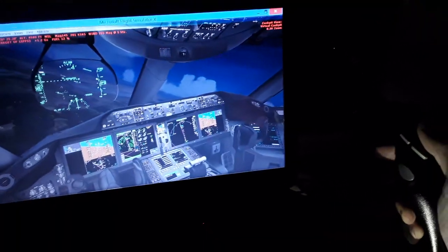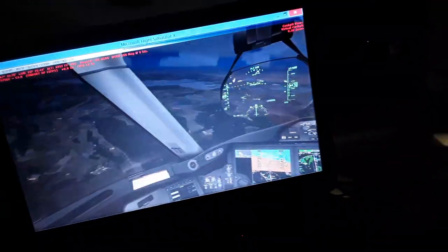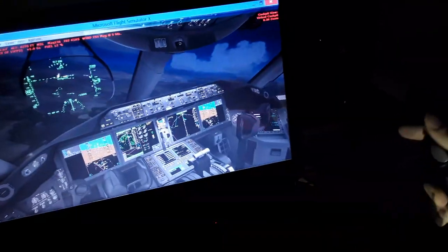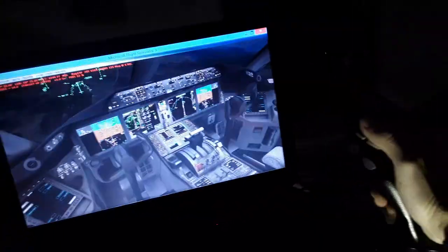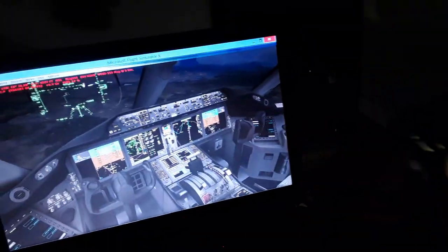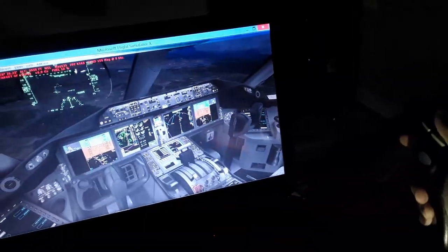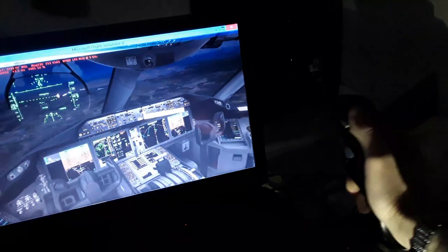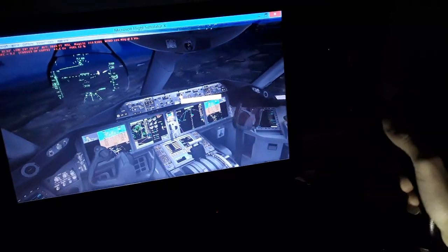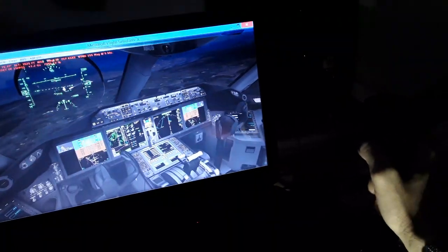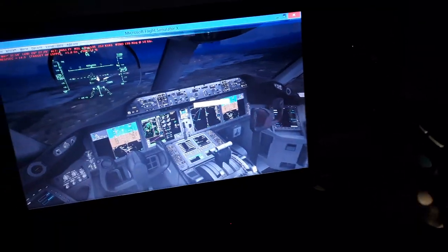We need to combat the side wind from time to time, because it makes the aircraft offset its trajectory to the runway. So we use manual flight controls, manual engine power, thrust over here available. Also use full flaps for approach and landing. Use some horizontal trim, stabilizers. So wind, we have some side wind and a lot of wind gust, and also wind shear as we approach. Wind gust means also wind shear.